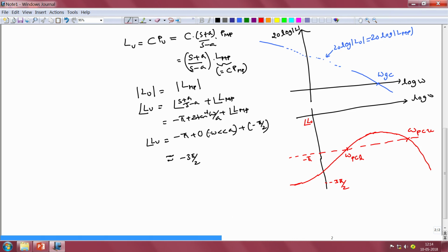So this is the phase characteristic, and that is the magnitude characteristic, and here is where our problem begins as control engineers. How can we determine whether an open loop system that has a Bode plot of the kind that I have drawn here is stable or not? For one thing, this is the first time that we are coming across a system that has two phase crossover frequencies.